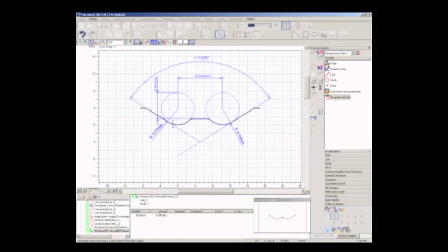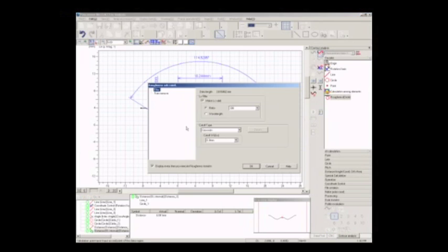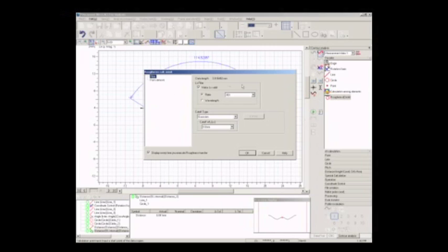The other thing that we want to do on this profile is measure a surface. For example, I'm going to measure a surface in this arc. I use the roughness of a circle so that the arc shape is removed before we do the filtering for the roughness. That would make sense. When I do that, this dialog pops up that allows me to set some things about the surface roughness.